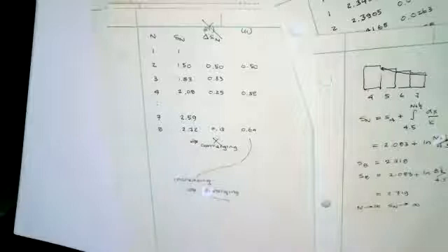The other system sounded nice in the beginning because it looked like it was easy, but eventually you're not changing your mesh by much. When you get to 9n and 10n, you're only changing it by 10%. Well, maybe your answer only changed by 10%. You think, well, that's good enough, I'll stop. Whereas when we go from mesh 9 to mesh 10, in 2D there'd be 4 times as many elements, and in 3D there'd be 8 times. So we're not changing the mesh by a small amount, we're changing it by a lot. And then if the answer doesn't change, this is pretty much the answer.